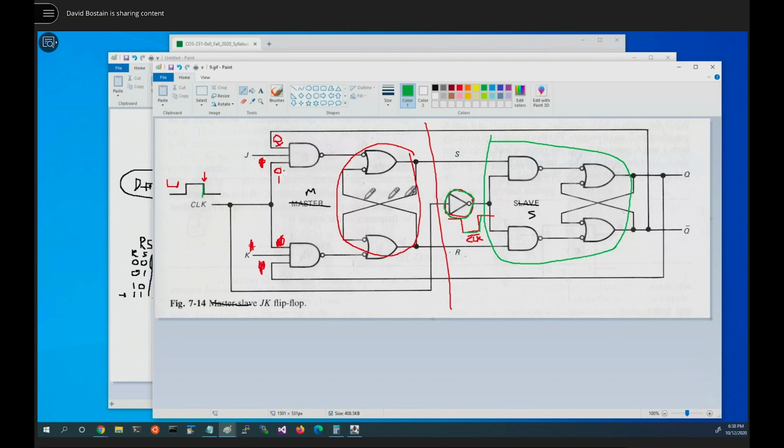So that means the only time we can latch anything from this stage into that stage is on the falling edge of this clock, which is the rising edge of this clock. Changing signals either while it's high here or low here will never affect anything past this clock. So we effectively have created an edge clock.